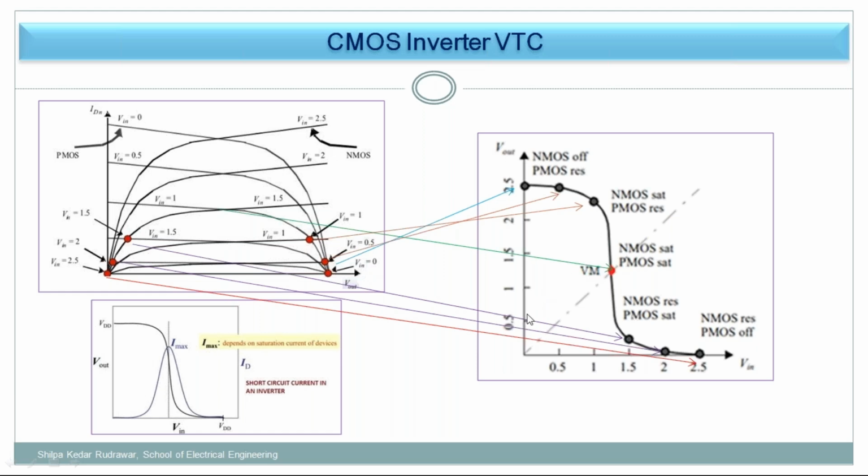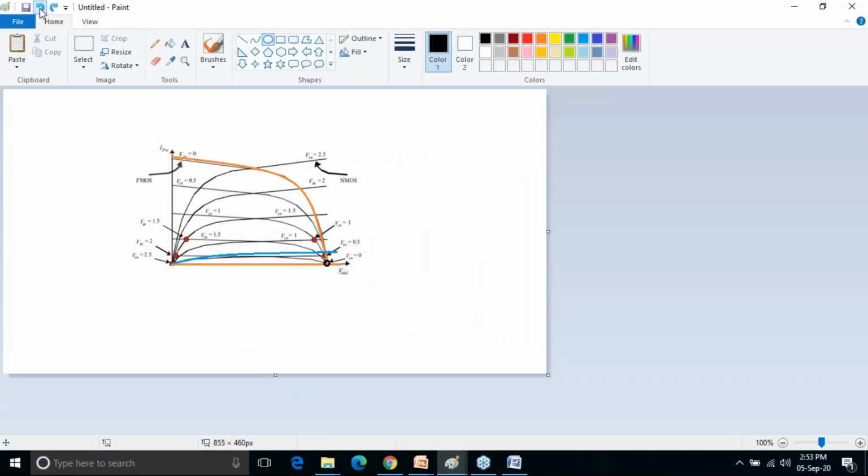So here I have just created this particular thing. See this, I have used a somewhat dark shade. Previously it was not visible. Just see when input is 0. I'm just telling when the input to the inverter circuit is 0. So I need to see the waveform of when PMOS Vin is 0 and NMOS Vin is 0. So where is the NMOS, PMOS Vin is 0? Are you able to see? This is the PMOS, as I told you in the previous graph. Just link it properly. This is very important. Okay. So this is the graph where the PMOS is having Vin as 0.